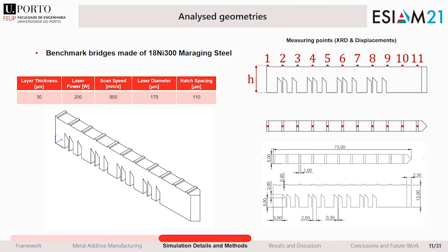After the residual stresses measurements, we also performed the cutting of the legs of the bridge, leaving attached to the base plate the right part of the bridge. With this cutting procedure, we will release some residual stresses, which yields a deflection of the bridge that was afterwards measured using a contacting probe.